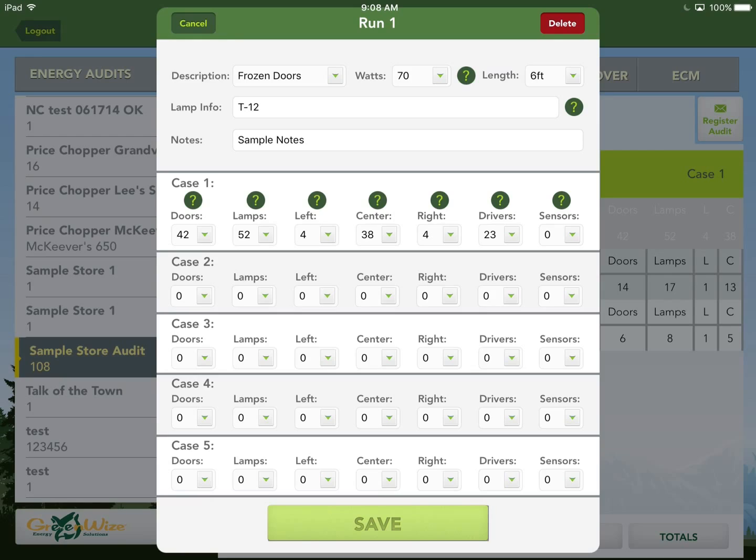So as you're doing that, just know that those old cases, they have a left and a right, and then one in between each door. When you put in new LED lamps, you can eliminate where the 2 cases meet up. You don't have to put a left and a right, you can put one center. So that's why you see 52 lamps in there for the existing, but only 46 total lamps for the new LED lights. Is because you don't have to have as many lamps as were in there before with the centers.